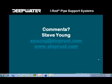Okay, and the next question is, how long would it take to replace the pipe supports? How long would it take? It depends on the company, I suppose. It seems to take longer for a company to make a decision to spend the money on that type of a project than it does to actually do the work. It doesn't take very long to actually do the work. You just lift the pipe up, install the I-rod. It's very simple to do.